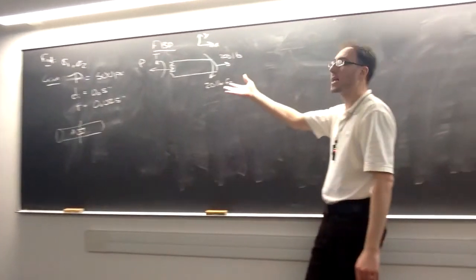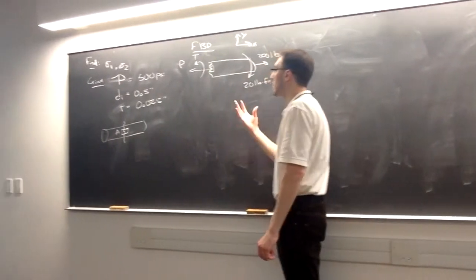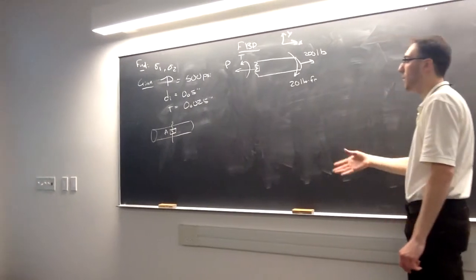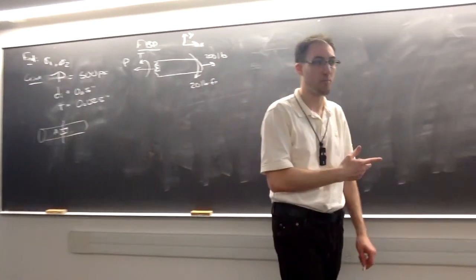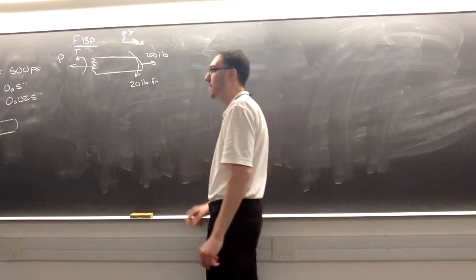I would also potentially have bending stress, things like that, but in this case, those are all going to go to zero. The shear forces will be zero. The bending stresses will be zero. I will only have a P and a T in this case, as well as I have to consider that internal pressure as another source of stress on my element, but I'll get to that in a minute.